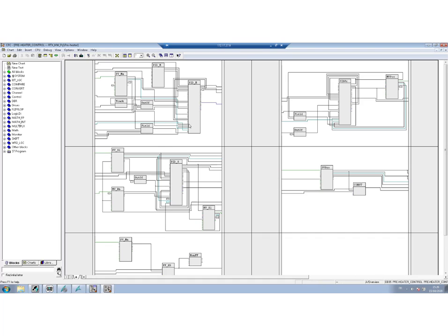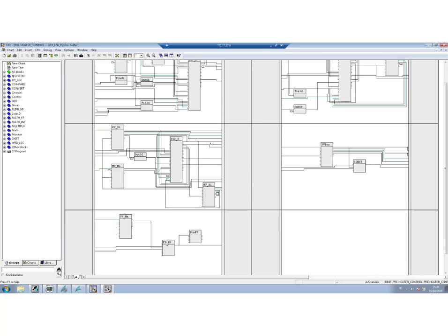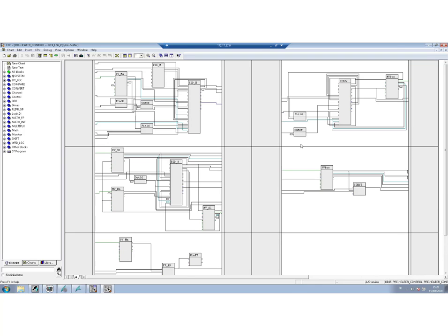What you see over here is the master controller. So this is the temperature controller, and this is the slave controller. So this is the fuel flow controller. This Cascade is very similar to what we have looked at previously when we had considered Cascade control. And what you have over here is the feed forward. We'll come back to that later. And here you have a PID controller that allows you to control the product flow.